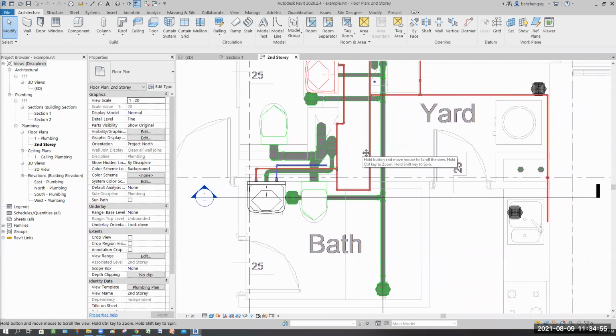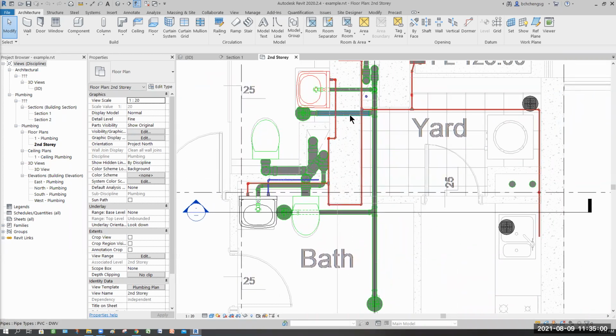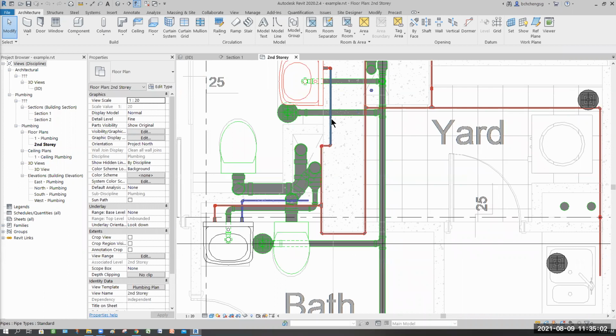I think some of them, when they were early, I did explain to them. See, this PVC pipe cuts through the column. Is it possible? Normally, no. But if it's a steel pipe, maybe yes, they can precast first. So it depends on your project. PVC normally, I don't think they allow you to do that. So you have to think of other design.